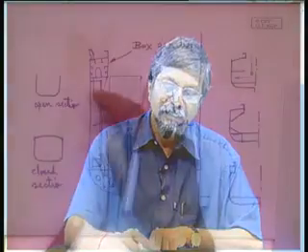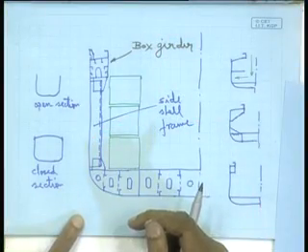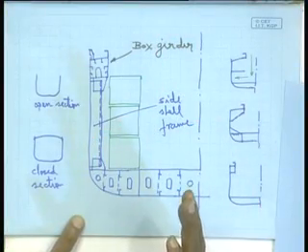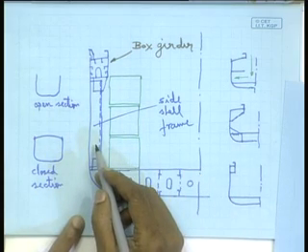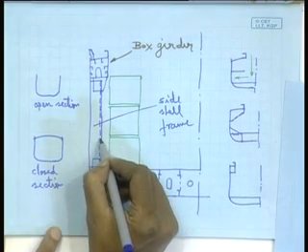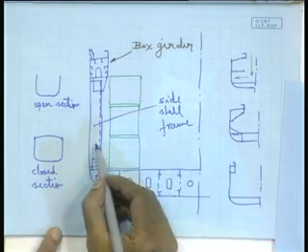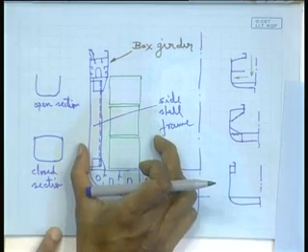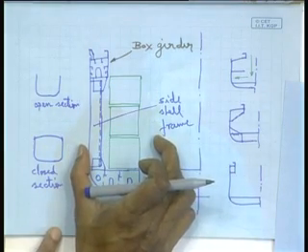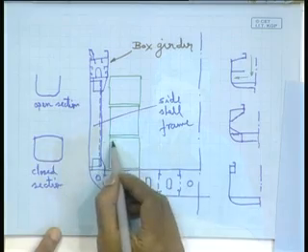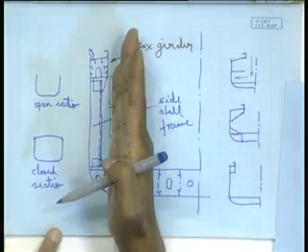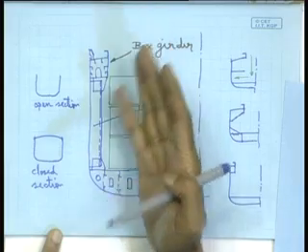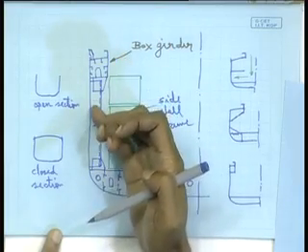So, what you see is that the side shell is transversely stiffened. Transverse framing arrangement is taken in the side shell. Why? Had it been a longitudinal framing system, then again the case of those too big transverses would have come, it could have encroached into the cargo space, I would have had to shift the boxes, and more space would have got wasted.